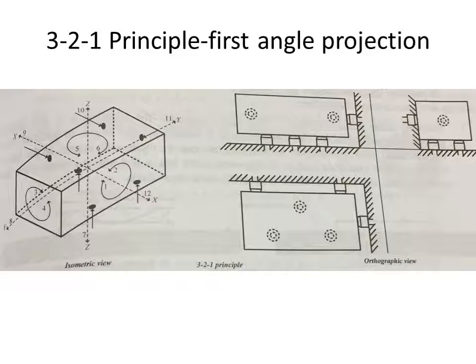in the front view, the component is placed on three locating pins or three supporting pins from the bottom. These three pins are set in the form of a triangle, and the component will sit without any shake on 3 points. Once it is located from the base with 3 points, how many degrees of freedom are arrested?